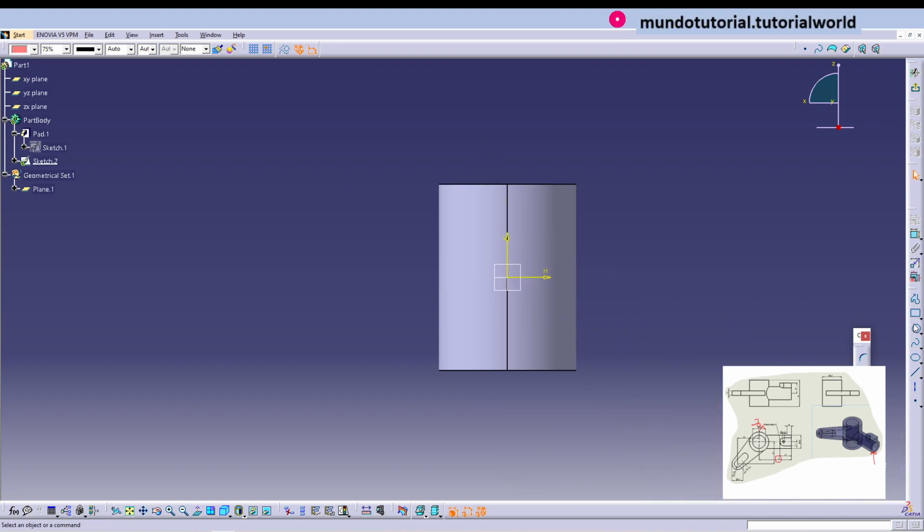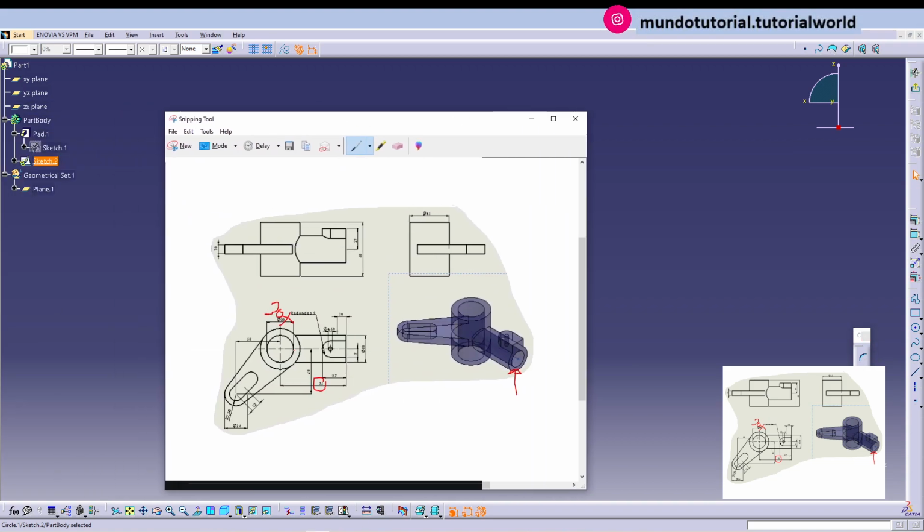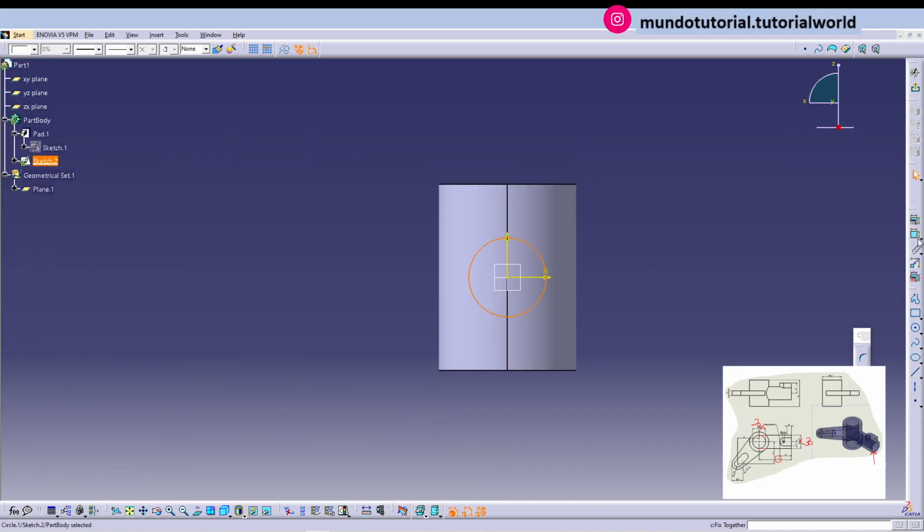Let's come here. Let's create here again another cylinder. So in external diameter, it says 20 again, but if you see, it is aligned with the diameter that we have changed to be 30. So I will change this to be 30 as well. So let's make this 30 millimeters, 30.